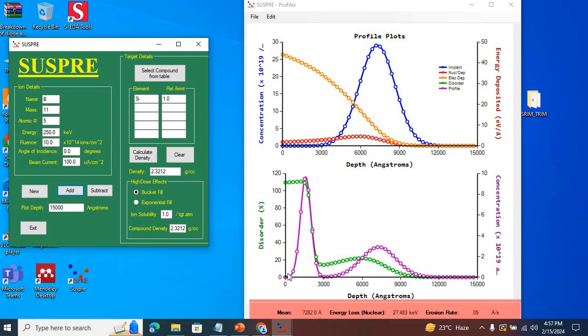Now we can see in the results that this peak is for arsenic doping of silicon, and the peak is observed at 10 to the power of 19 per centimeter cube for arsenic doping of silicon. The second peak over here is for boron doping of silicon, which is observed at around 728 nanometers at a peak carrier concentration of 3 times 10 to the power of 19 per centimeter cube.